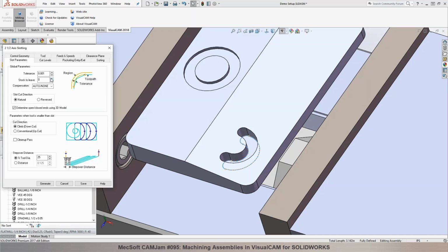We plan on using manual tool change where we have end mills and collets. They're just standard R8 collets. I notice a lot of these have the length specified and things like that. How do you manage that when you're doing this manually? Do you have to measure it out to make sure that you have the same clearance, or is it okay if you just kind of eyeball it?